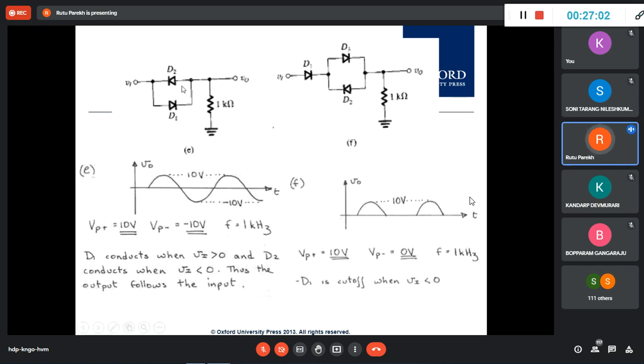So here also you took ideal. If it is constant voltage drop, then instead of 10 volt, you will have 10 minus 0.7, so 9.3. But when you are working with high voltages, let's say I'm giving 100 volt here, and this is just 0.7, what will come out here is 99.3. So that is fine when I'm working with it, I don't care about the little drop. Do you understand my point?